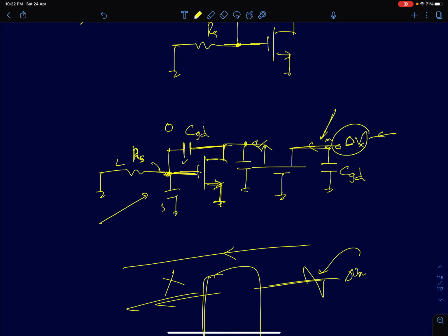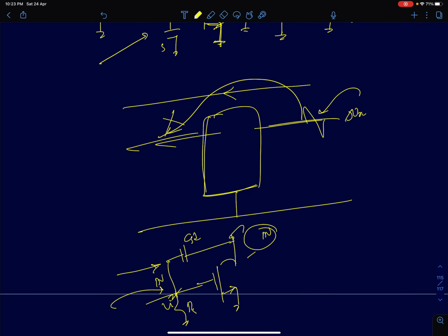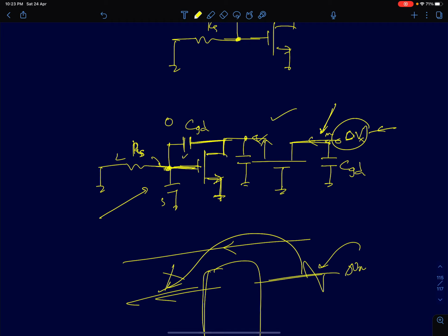That's the other benefit a cascode amplifier offers. We don't want any output signal to be coupled back to the input. That's what isolation is for. Cascode amplifiers give you very good isolation, and the isolation comes from the common gate structure. It's the common gate which provides you the isolation, because the reverse gain of a common gate is very small. We saw that approximately, if you include R0, it will be very close to 1 by 1 plus gm R0. So it's attenuating the signal significantly. That's where the benefit for isolation in cascodes comes from.